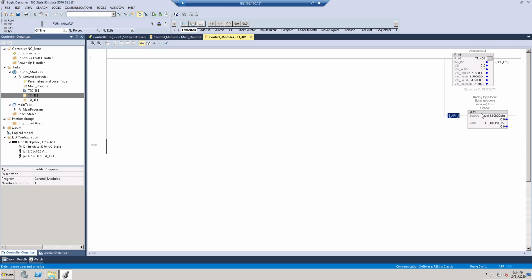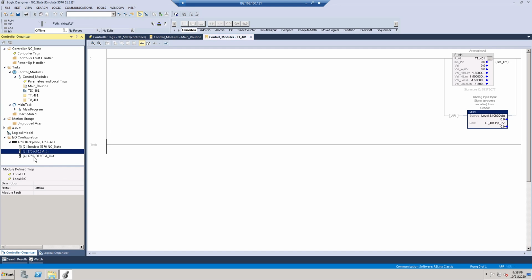So it's pretty much when the code actually goes live, it won't evaluate it, because I made 2 I/O modules just as examples. This is an analog input module, and then this is an analog output module, which is if this was a real system and we were actually running copper wires out to these temperature probes and control valves. The temperature probe, the input value to the PLC would actually get landed in a specific slot and channel.